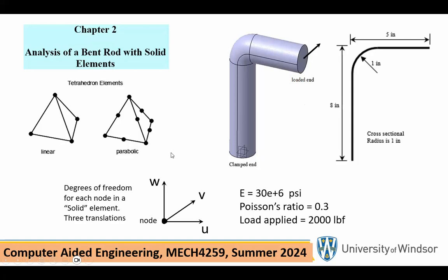And the thing that you have to keep in mind is that when you're using solid elements, which I'm referring to here, each node has 3 unknowns associated with it, displacement in x, y, and z direction. So the degrees of freedom associated with each node in a solid element, tetrahedral element, is 3. We'll see what happens with beam elements or later on shell elements.